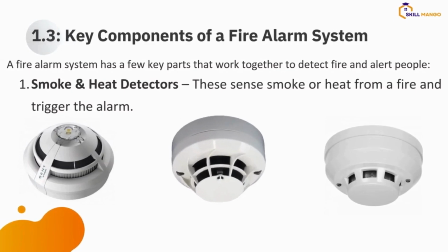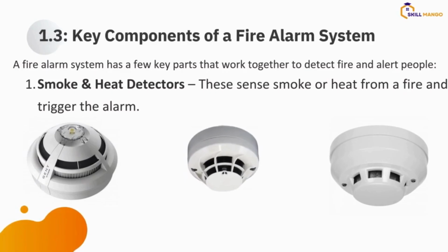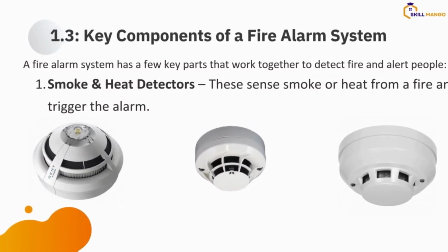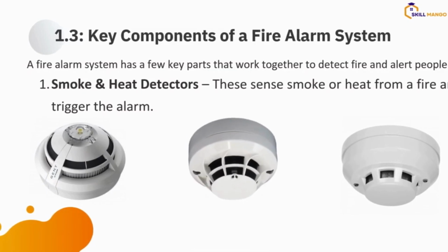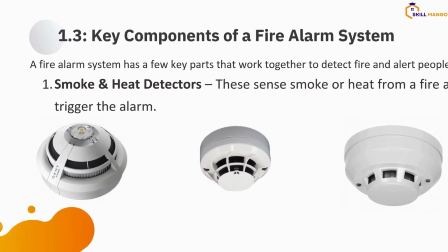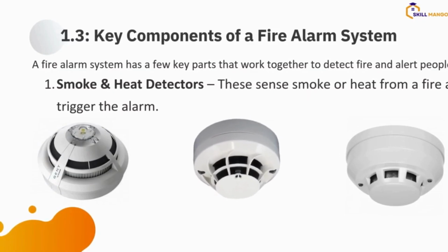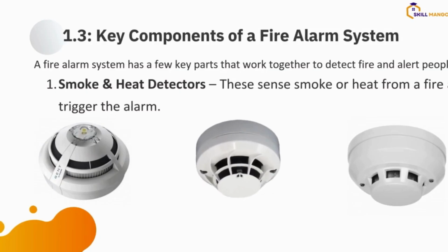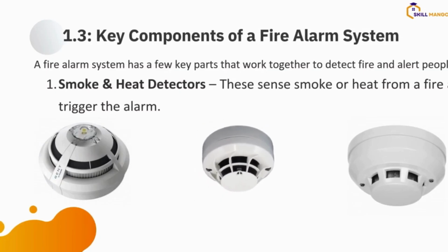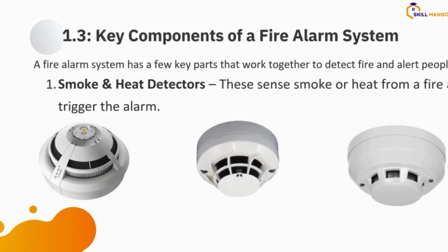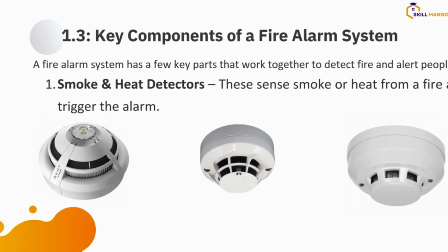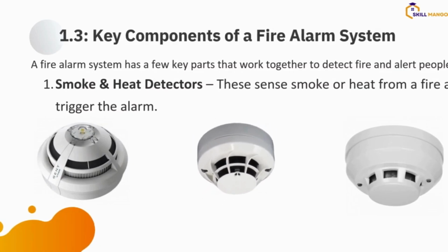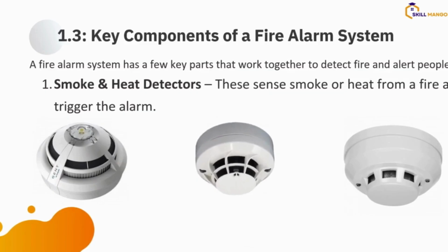It's a combination of different devices, which are the smoke detectors, the heat detectors, the MCP and the FACP. Then the cables, the fire resistant cable, in some cases we have the end of line resistors. Sometimes we have the communication module to be able to transmit and send alerts, calls or notifications to the fire service and the fire centers. Sometimes we use the GSM fixed wireless terminals to send out alerts to fire service.